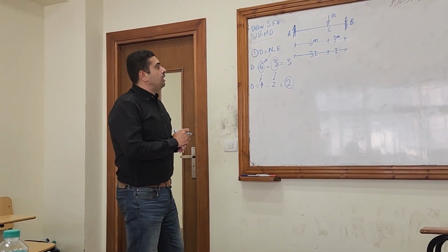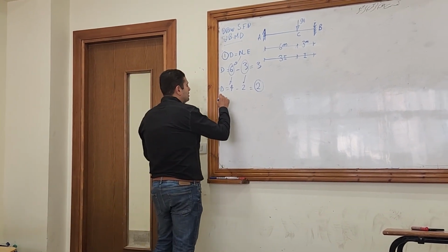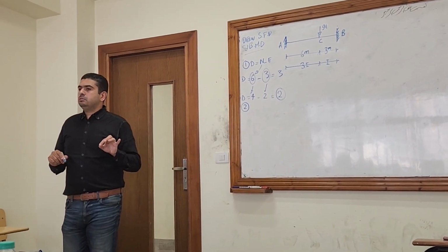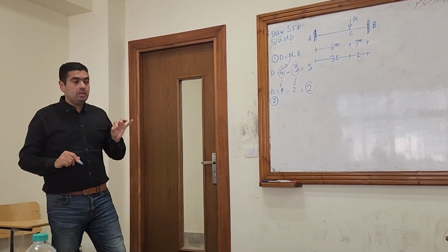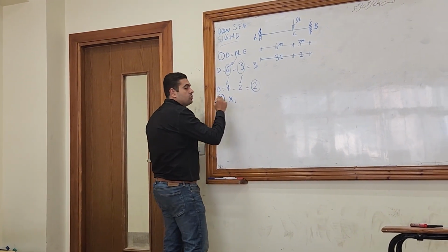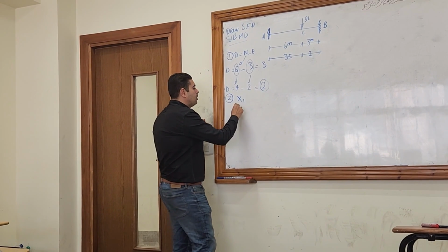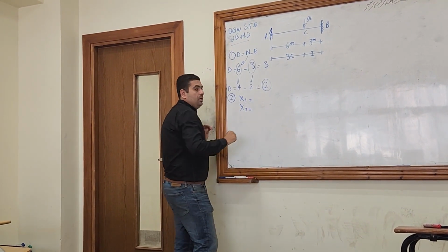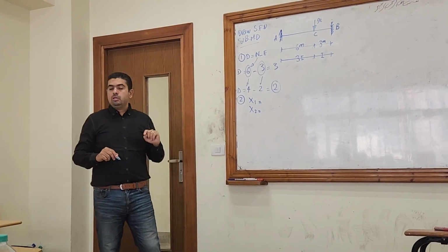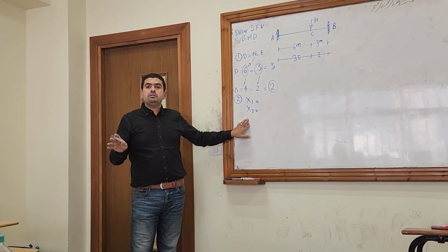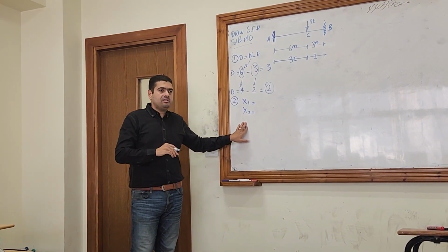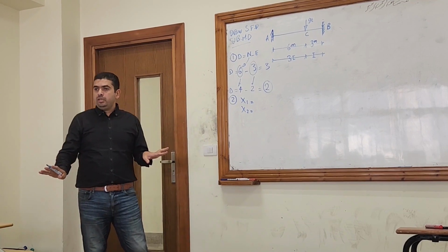Right? I have to decide here in the second step the naming of each redundant. It's very important, the naming. Which one of them will be called X1 and which one will be X2, because the whole solution will depend on the naming here. Here you are free to decide. Either MA is X1 or MB is X1. It's totally up to you, okay?